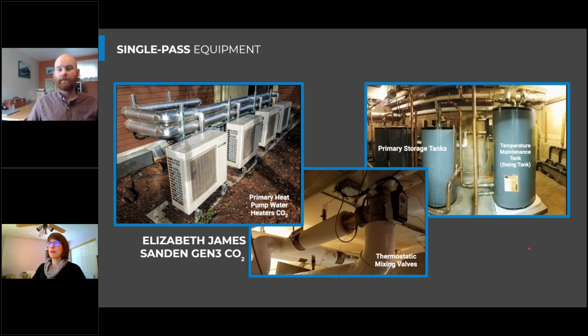Quick question, Colin, about the piping and the sizing here. It says, what is the pipe sizing on these apartments for the exterior piping? It looks like they're super insulated. Yeah, so out here, we actually have 2 inches of insulation on this pipe, and it's a 3/4 inch pipe that then steps down to 1/2 inch connections to go to these Sanden units. So we have about 2 inches of insulation and then a metal jacket to prevent birds and other critters from damaging that.